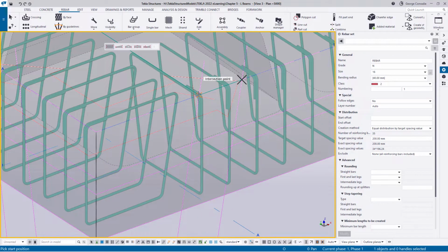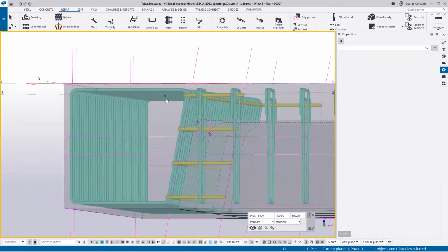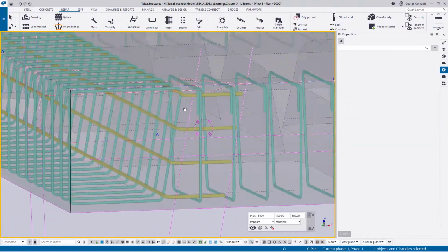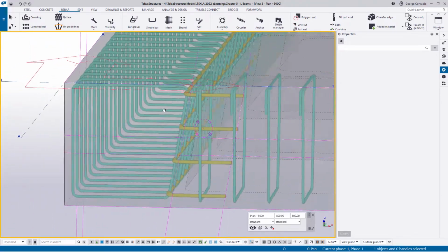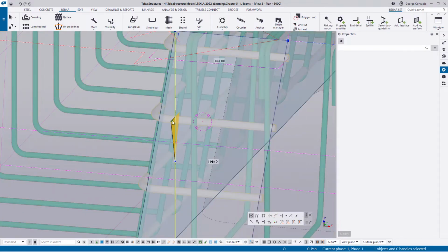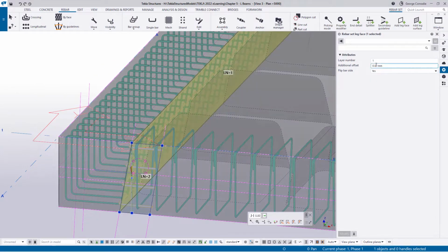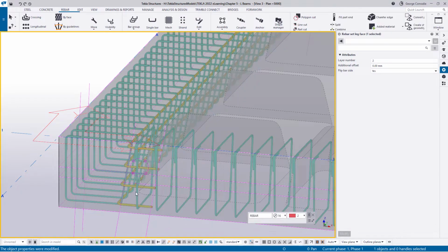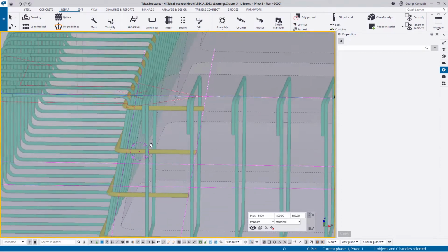And then for the range, if you pick a range from there to there, for instance, that will work. But the problem here is that, well, that's actually worked quite well. Maybe we can get away with this. Okay, now all we need to do is deal with the issue that this face here says it's in level 1. It should be in level 2. And sometimes you need to do this twice before it registers, and there it registers now. And now we can see that's actually worked out quite well. I think I'll just leave it like that.